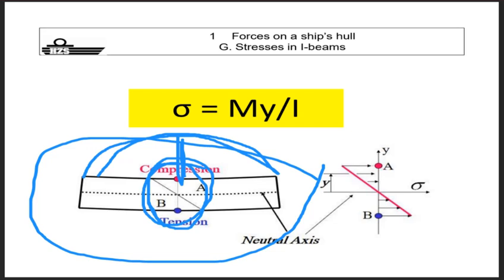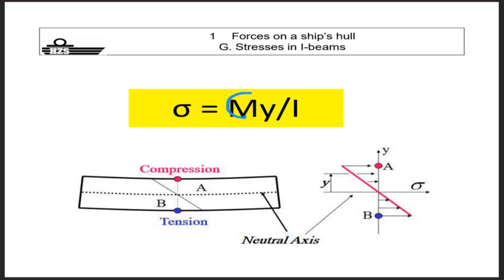When your bending moments are very big, your moment is big, it's proportional to your stresses, which means your stresses are big. So you take the worst case scenario where your bending moment is max to see whether yes or no you comply with staying below your yield point. What else do you need in this formula? The moment, of course, maximum moment, worst case scenario, and the resistance against bending. Why? Of course, because it's 100% linked to your stress level, depending on the shape of your vessel.